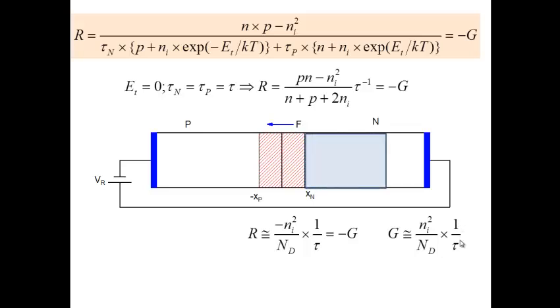And then what we are saying is the following. You generate carriers here, you generate electrons and holes, but, now remember, you are generating holes and they can recombine also. Holes which are within the diffusion length can actually reach this particular depletion region and escape and give rise to current. So you are getting generation all over like this here, but only within this region can they contribute to current. Okay, so what we are saying is that you take a length equal to L_p, the diffusion length, and you look at the generation rate in this region here. This is the generation rate per unit volume. If you multiply it by L_p, you get the total number of holes which are generated in this region.